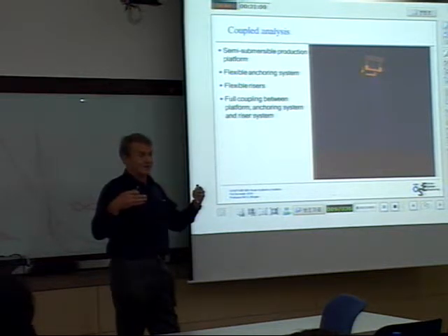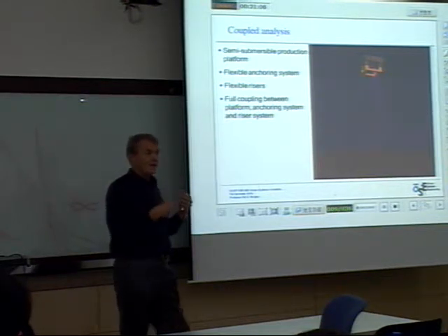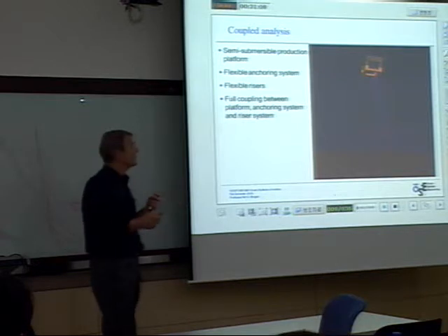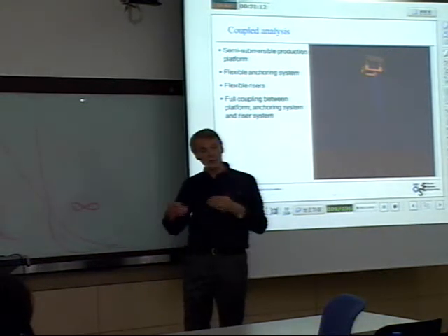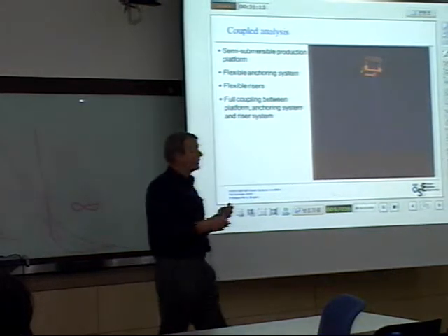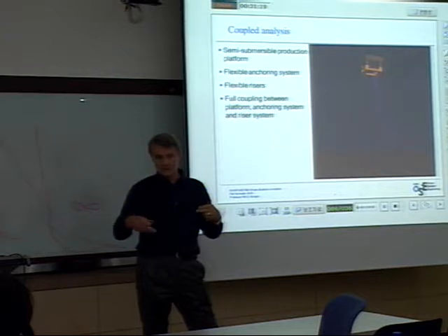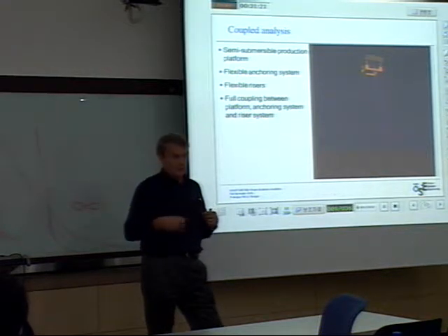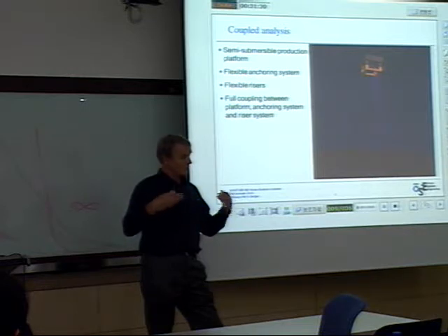serious sea state, which can be described statistically. From the statistical distribution of waves, one can have load transfer functions onto the platform and do a time simulation on that basis, or one can do a frequency response analysis. But if the system is very nonlinear, then you have to do a time simulation.